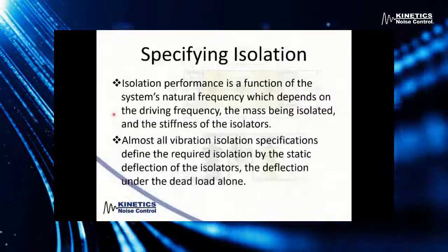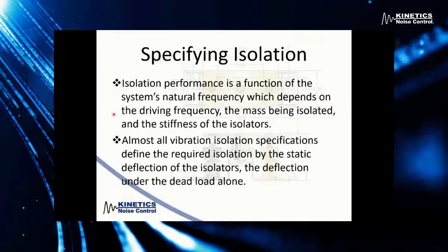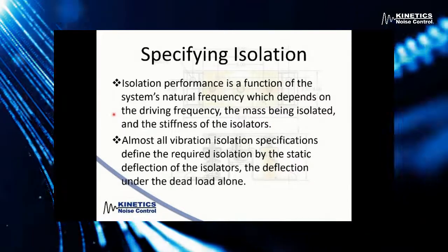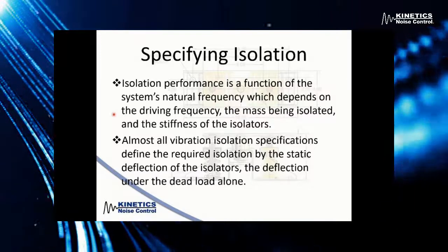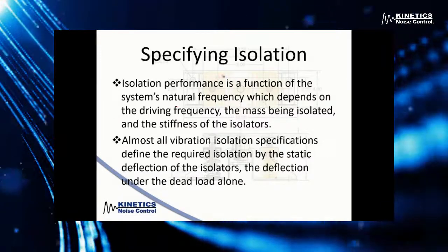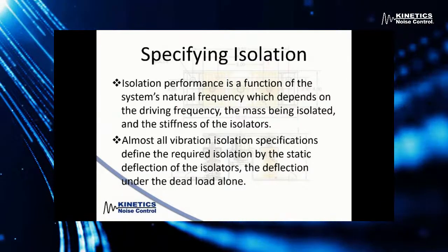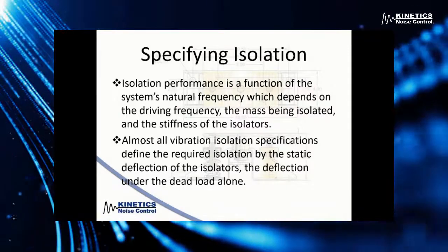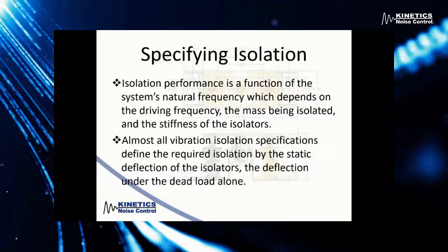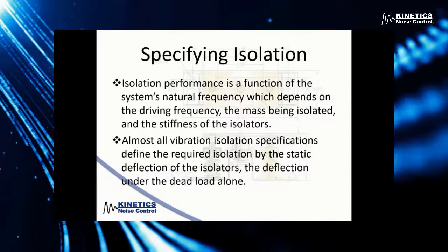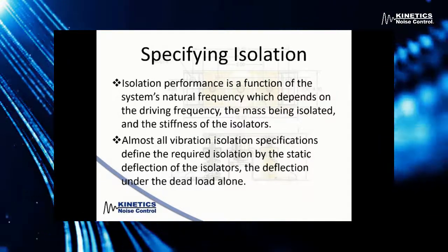Almost all vibration isolation specifications define the required isolation by the static deflection of the isolators themselves under dead load. What that means is, once the weight of the equipment is on the isolator, how much deflection are we going to have?